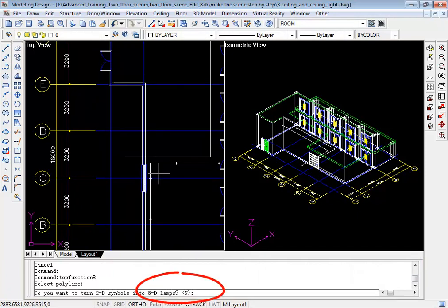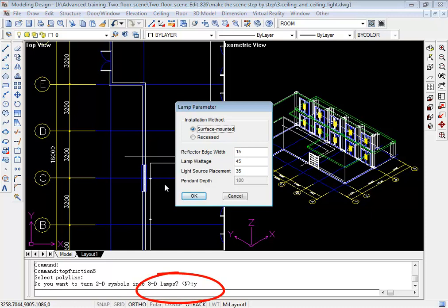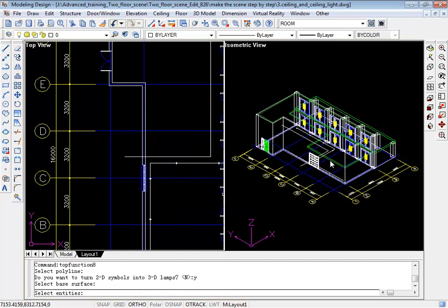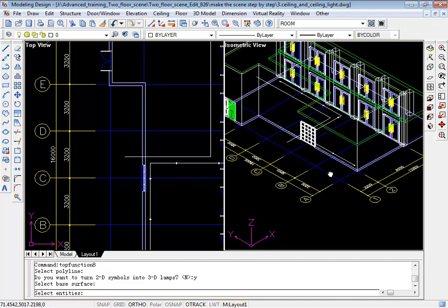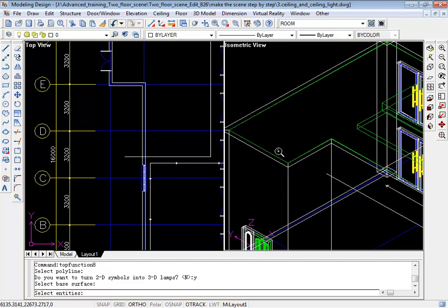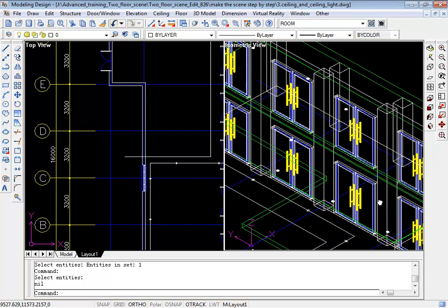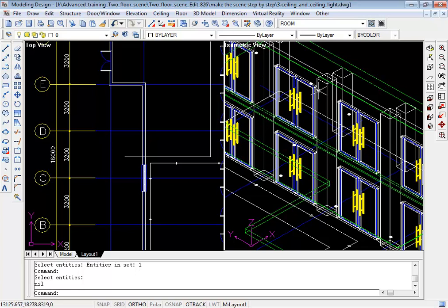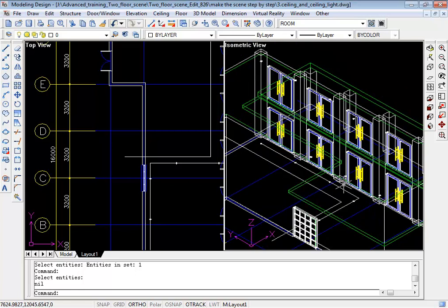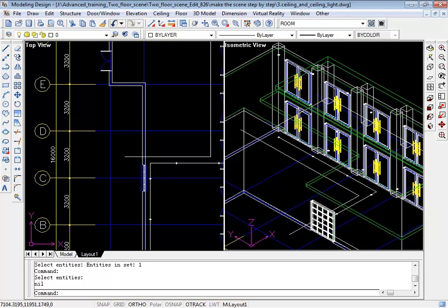Now look here. The system will ask if you want to convert these lights. Then we type in Y to say yes, and find the surface, which is the ceiling of the second floor. Find the green frame on the top, select it, and right click to confirm. Now we see the lights are created on that ceiling. Let's check over, see if they are on the right surface. They seem good. We can also give power, color, or other attributes to these physical lights, but now